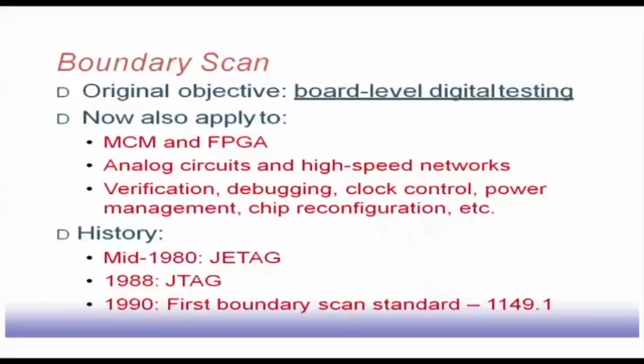Basically it becomes a tool to command various chips. If a chip has different power modes, and you want to change the power mode of the chip, then you can send a command via this boundary scan. There may be an interpreter or analyzer available at the chip input, which will look into this command coming from the boundary scan, and accordingly it may reconfigure the chip to go into a low power mode. So that way we can use this.